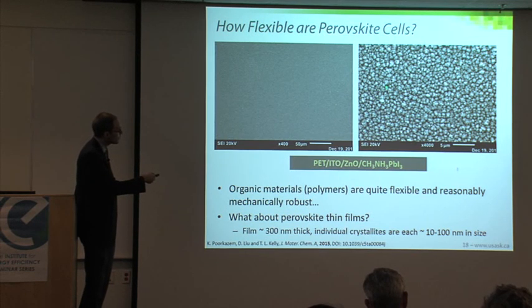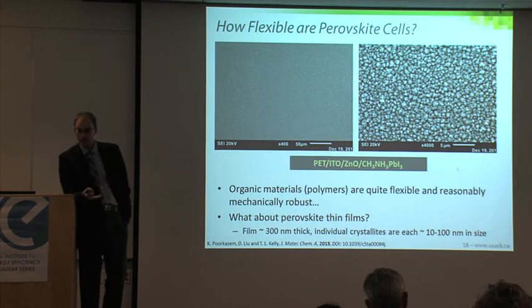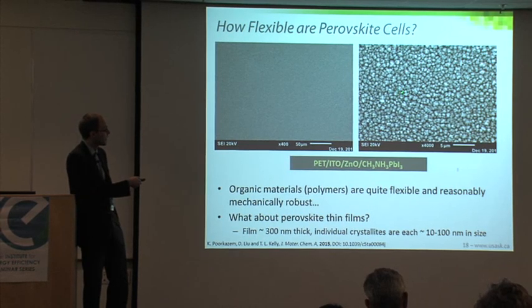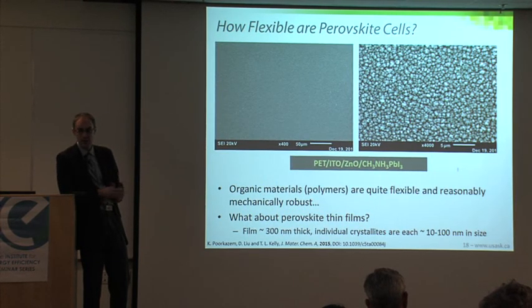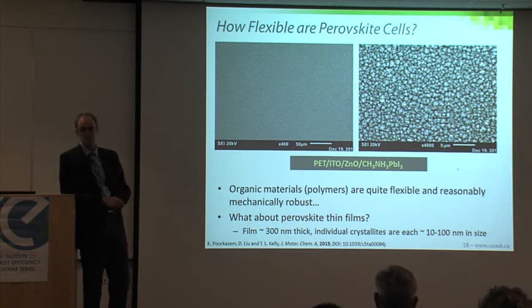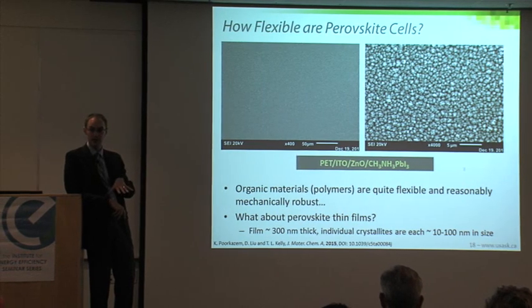And if you can imagine this being now a film that's 100 nanometers thick or 150, if you get contact through these gaps, you end up with more recombination that way, simply by micro shorts across or through the device. So I think that contributes a lot to the loss of fill factor at the very thin thicknesses.